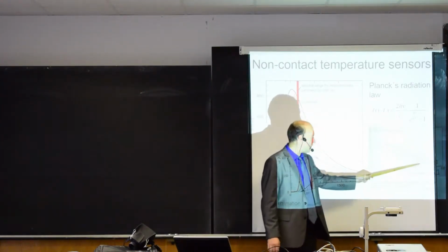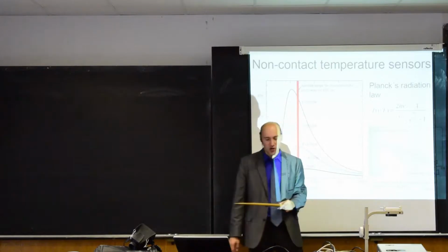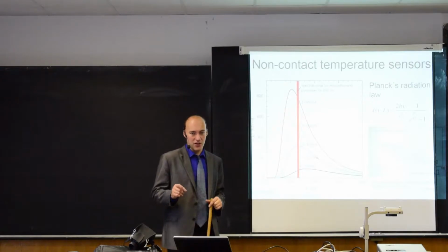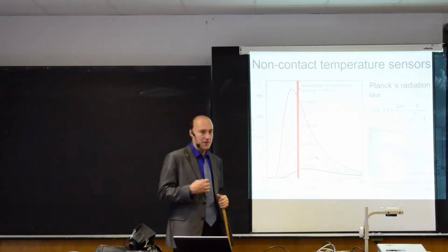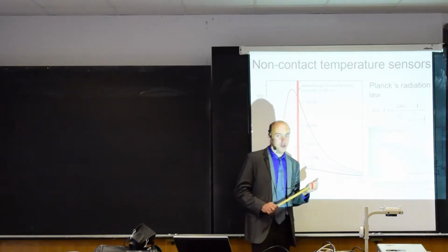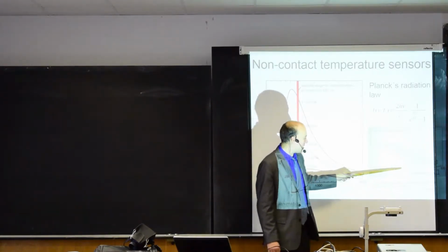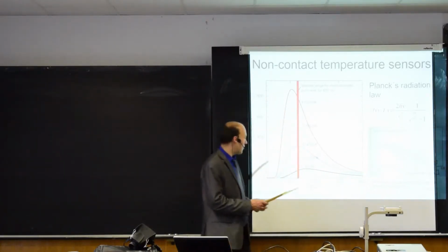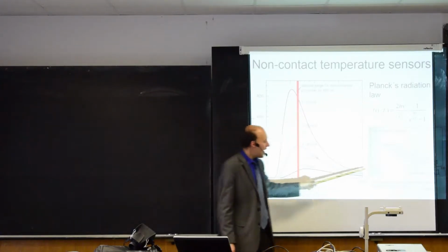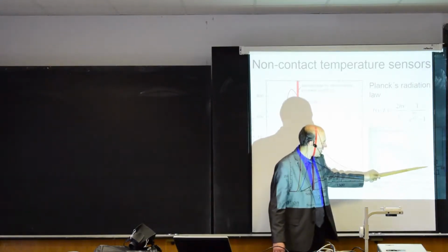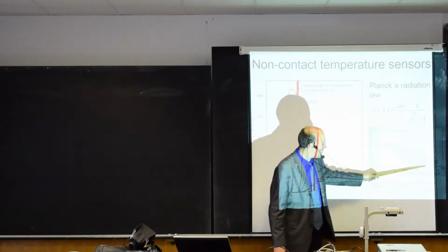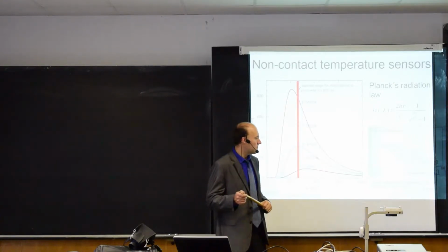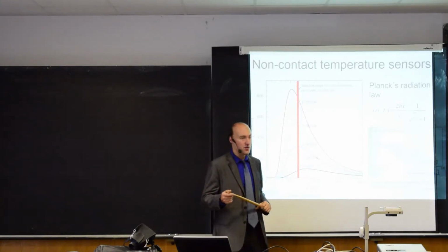Here you have a chart that is showing you 90% of emitted radiation, or the energy that you receive for a specific temperature of the object. So let's say we have an object with temperature 0 centigrade. So 90% from this curve is between 5 and, let's say, 30 micrometers. So it's a really far infrared range, and we'll see we'll need different optics and different materials for that.